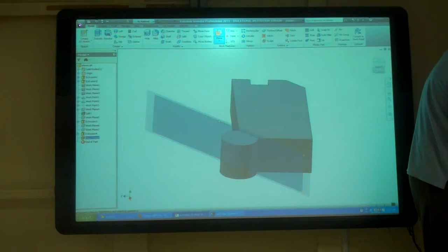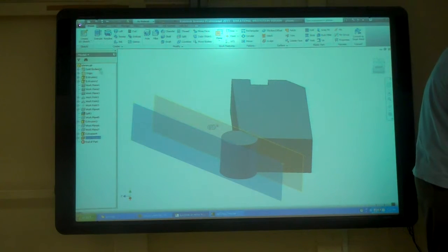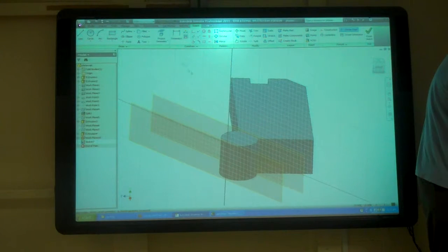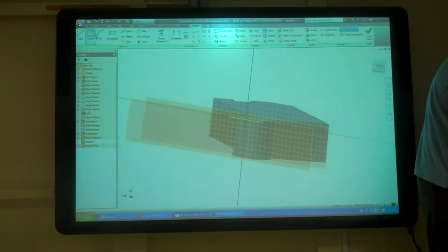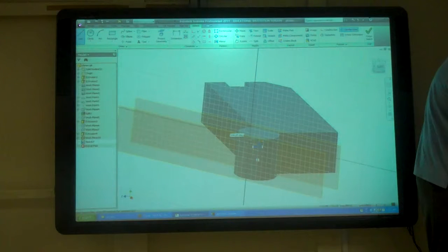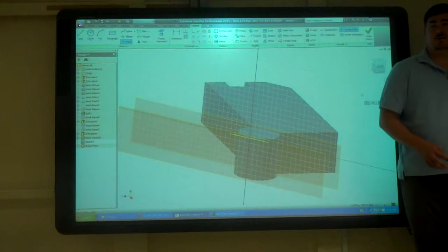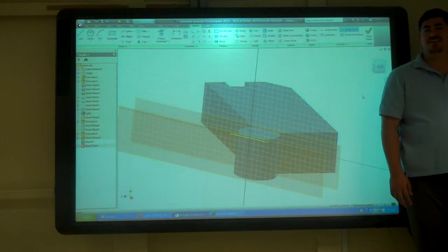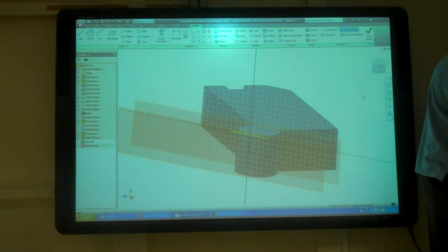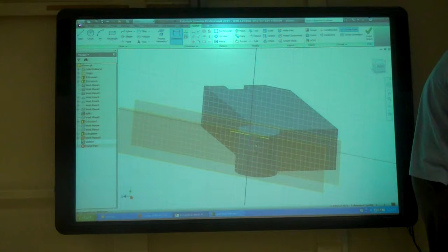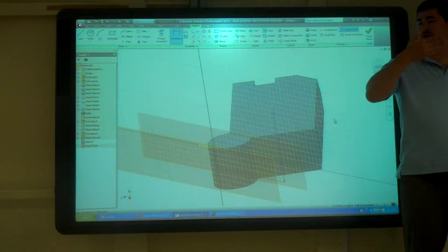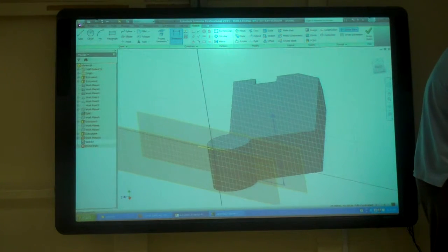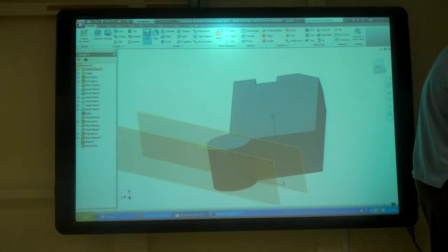So the way to get around it is now you have that sketch there. Create a sketch. I project that edge. Now I can just draw a line from there straight down and put a point on it. That should look familiar. If I graded your lab one, we did that same kind of thing. Then I can give it a dimension. Now I have a point there on a sketch plane that I can use to make the hole. I can finish. Now I can go hole.